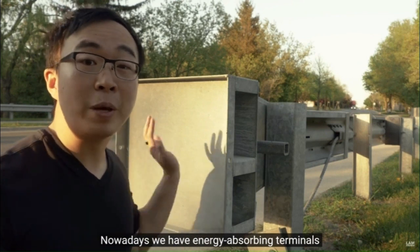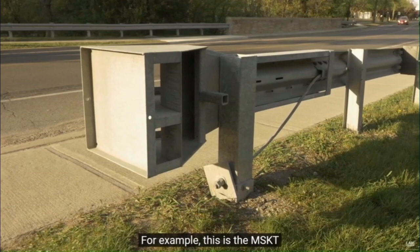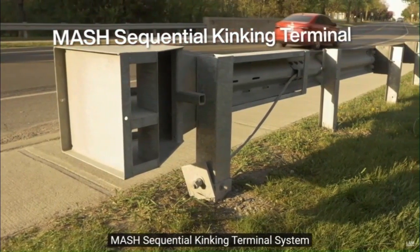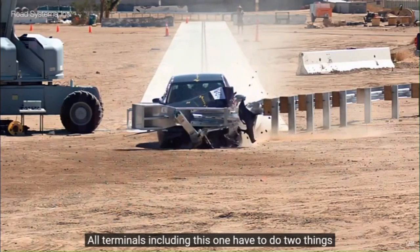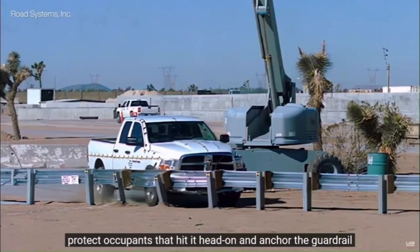Nowadays, we have energy-absorbing terminals that let people walk away from highway speed crashes. For example, this is the MSKT, MASH Sequential Kinking Terminal System, and costs around $3,000 US. All terminals, including this one, have to do two things: protect occupants that hit it head-on and anchor the guardrail.